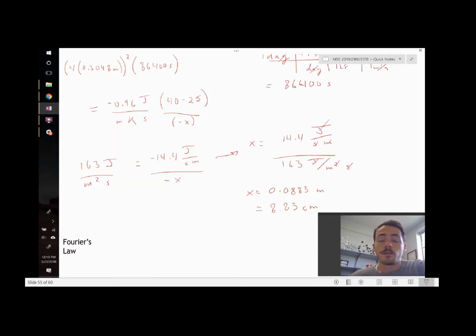Sometimes they even fill that, instead of with air, with an inert gas like krypton or argon, or a vacuum, different ways. And that would now become a double-paned window. And you can do triple-paned and make it even better. Or you could even move away from silica to something like polymers. Many polymers that are transparent have much lower thermal conductivity. But those are the things you would have to do if you wanted to have the same low flux of heat with the same dimension of your window, but making it thinner.